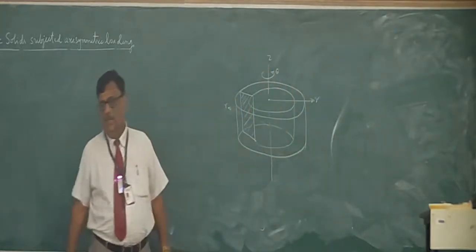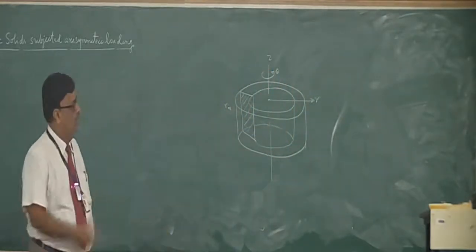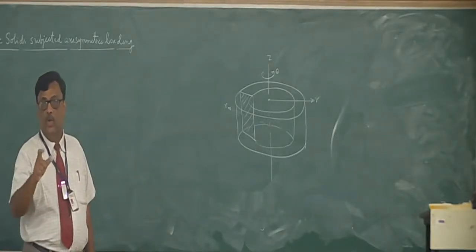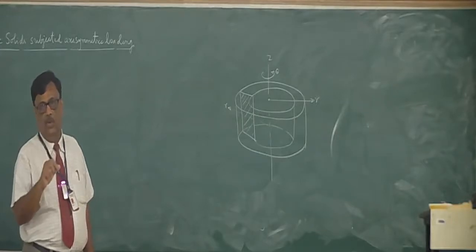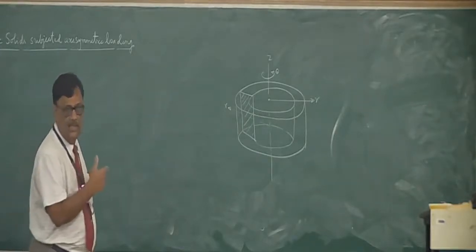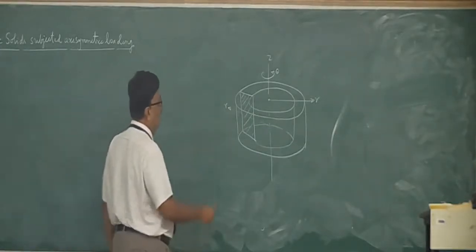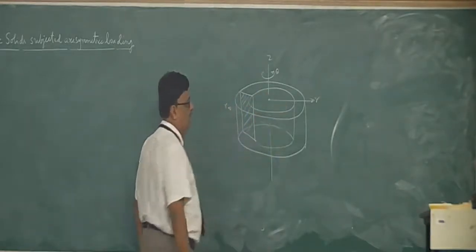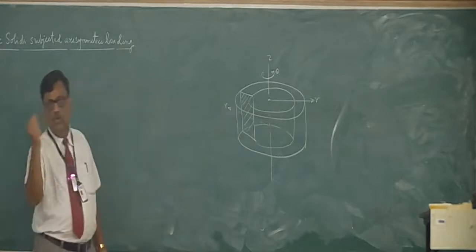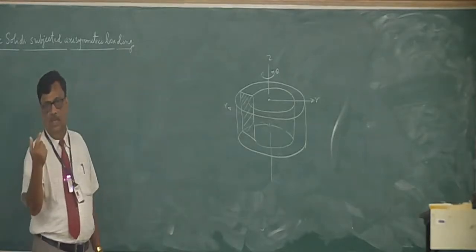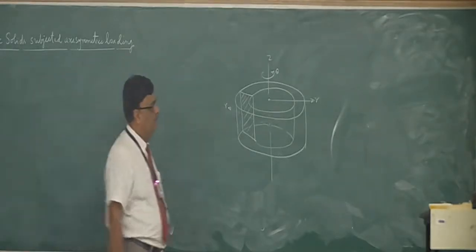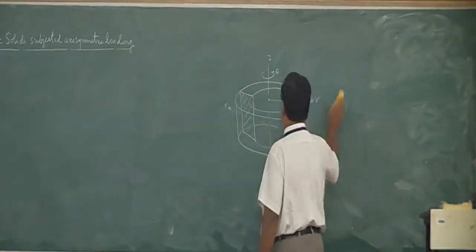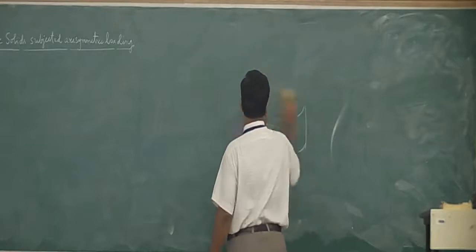But interestingly, because of the symmetry, this type of solid of revolution can be treated as a two-dimensional element only. For example, the stresses and strains are going to act only in the RZ plane. It can be considered as a simple ordinary plane, and the stresses remain the same everywhere around theta. Therefore, axisymmetric problems, which are three-dimensional, are converted into two-dimensional analysis.